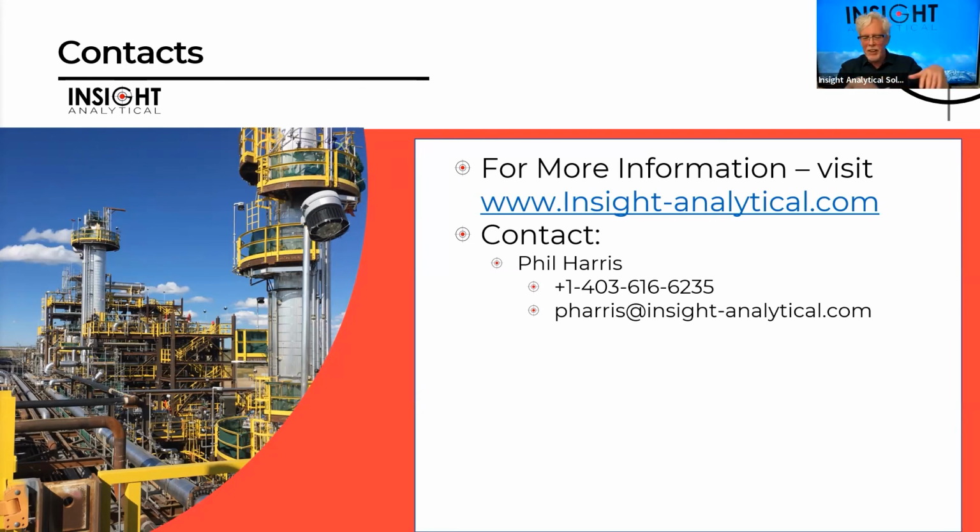Oh, you just went off spec for gasoline. Now you're on spec for diesel. So as different products are flowing down the pipeline, they can use the analyzer to figure out what product that is and whether it is meeting specification. And in that period of time when it's transitioning between two, it tells you how long that blend period is and whether you have to put that to storage for reprocessing.